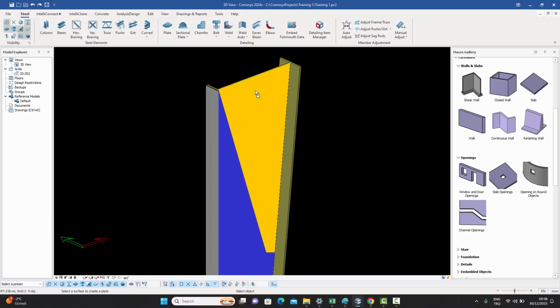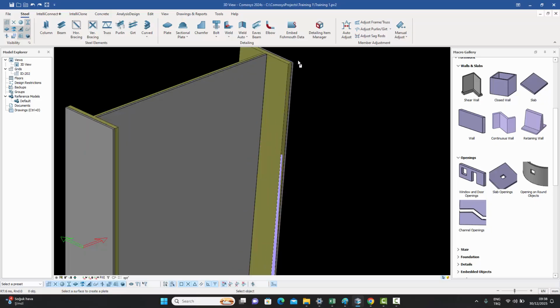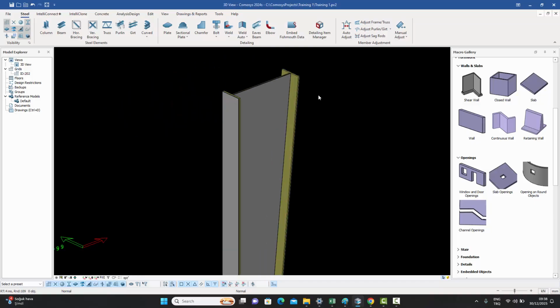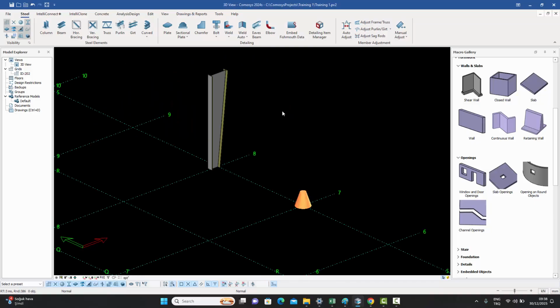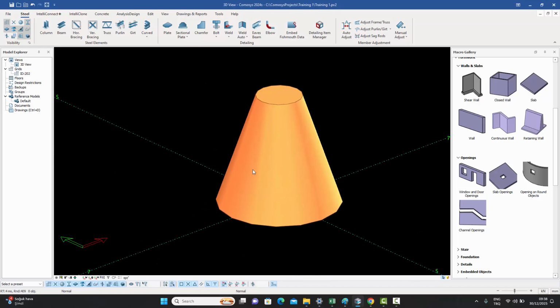And you can select another surface. Let's say you want to select it from here. You press Control, you get the back one. You can create a plate over there, and then you can offset those plates to get them where you want. You could use this command in more complicated situations. For example, if you wanted to create a cylindrical bent plate, you could just go in there and say, I want to create a plate on these surfaces.